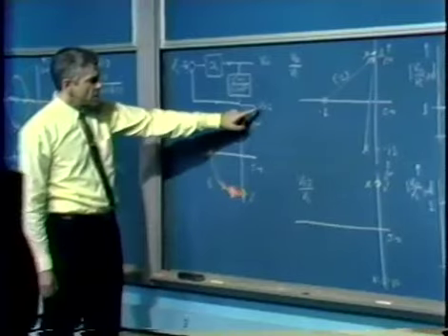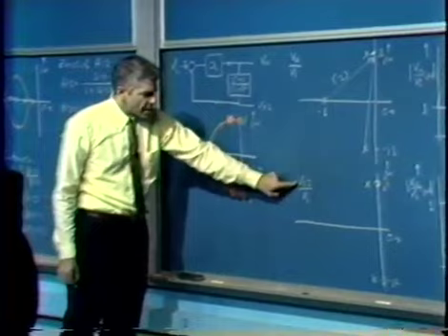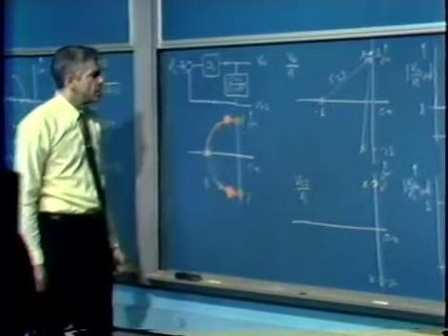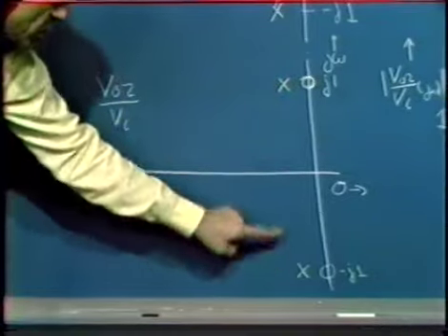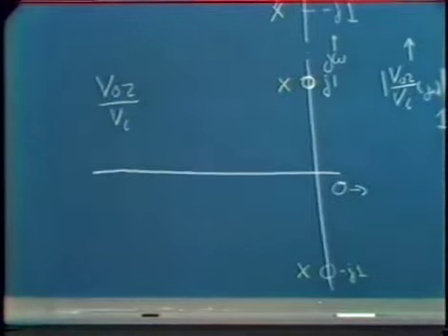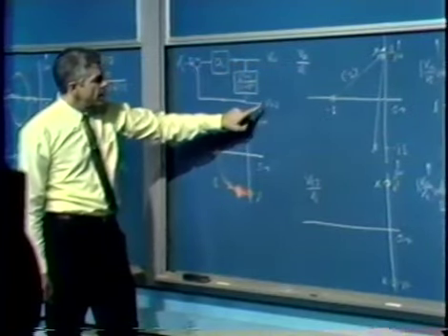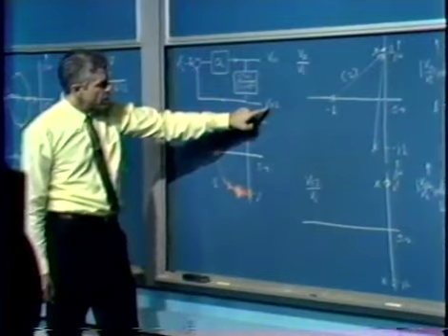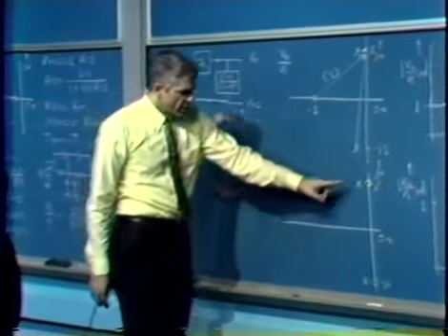If we consider the second system, or the second possibility, in particular looking at the second output as a function of input, we get exactly the same closed-loop poles, we must, but now the closed-loop zeros are those associated with the T network, because in this case the T is in the forward path, and so our Vout2 over Vi1 must include zeros at the zeros of the T network. And so we get this sort of behavior.